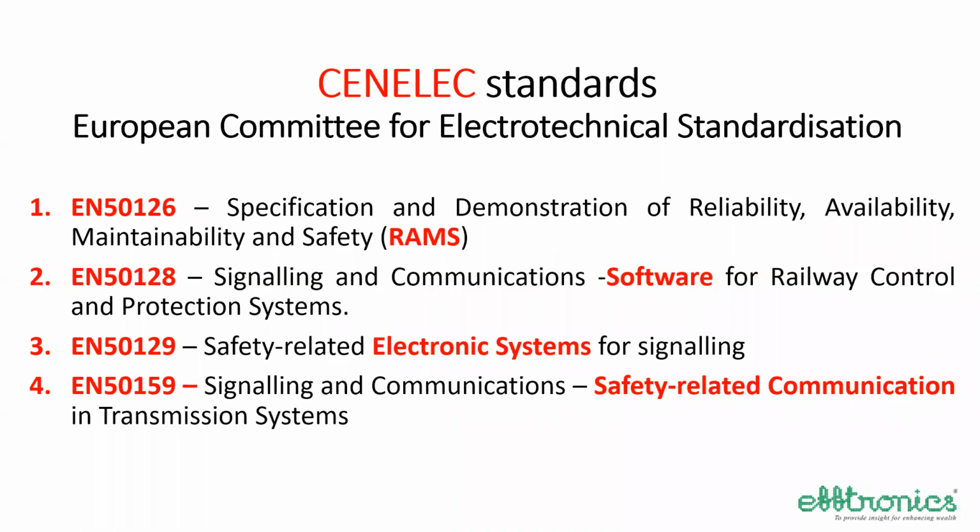It is compulsory actually, because to get the SIL4 certification, safety assessment is done based on these 4 types of standards. The first one talks about reliability, availability, maintainability, and safety, and how it is done. The second one is about the software design. The third one is about the hardware and software together when they are working, mainly from the hardware point of view, also how they are taking care of the safety. The fourth one is related to communication. If communication is taking place between 2 systems by exchanging data, how does it happen in a fail-safe way? What are the processes that are to be ensured?